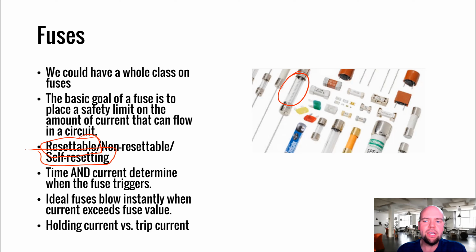They cost a lot of money because they are designed to rapidly open circuit immediately when we exceed a current threshold. Those fuses are for protecting very sensitive, very expensive electronics, and so we pay extra for fuses that will quickly blow. That's not the case necessarily with the fuses in your house or in your car or elsewhere.